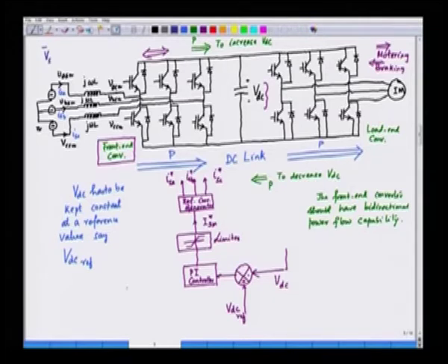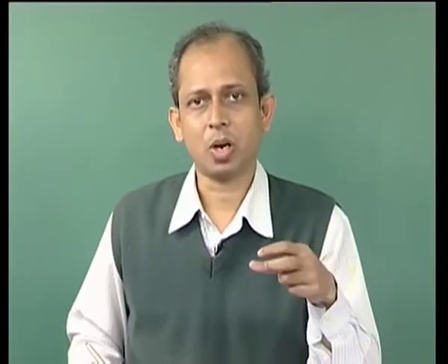We represent the voltage by means of a phasor, and then we have a reactance, and then we have a converter which is Vc, and the current flowing through the reactance or the inductance here is Is, this is also a phasor, and the value of the reactance is omega L. So, if we replace this in per phase quantity and try to write down the phasor equation, we can say that the source is supplying two quantities, one is the reactance drop, other is the converter voltage.